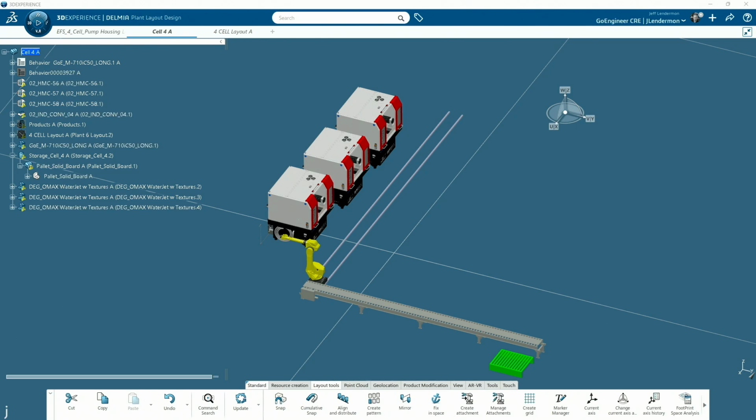So Don mentioned the robot programmer. There are some other tools that we can work with the kinematics of a robot if you don't have a robot programmer. That's how I worked with this one. But the catalog of robots also has, like he said, home positions. So if I bring in a robot from the system that has home positions, I can use those in plant, in factory flow, which I'll show here in a minute. And Plant Layout does come with the robot library. So it comes with over 2,200 different robot models with all the kinematics in them. So it does come with that.